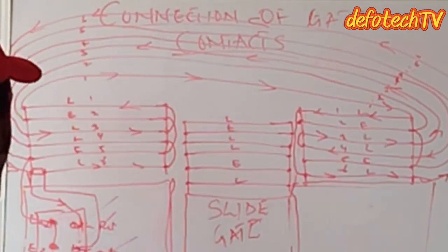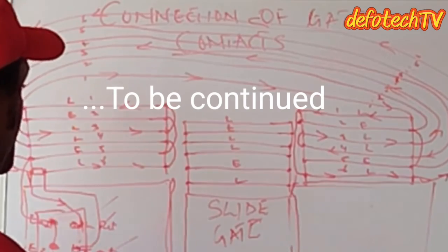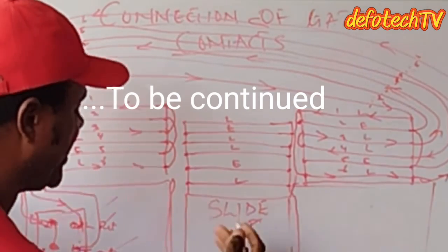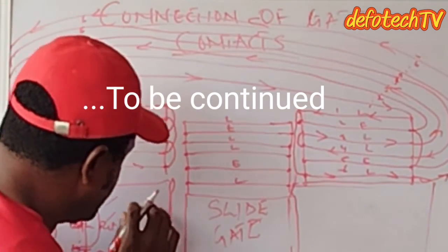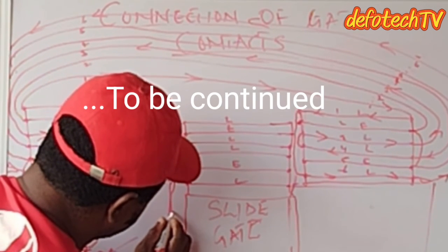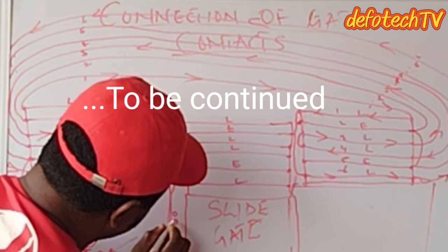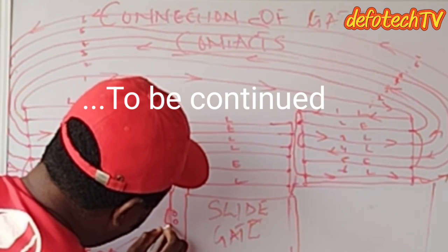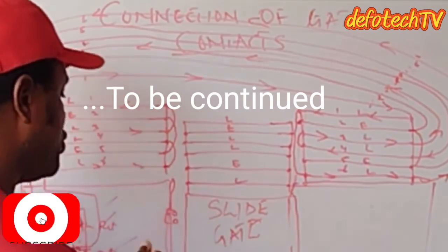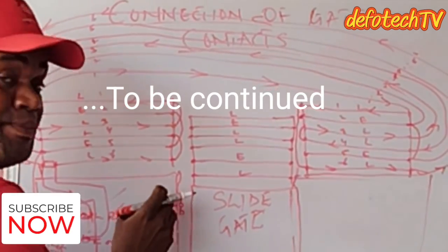Like we explained in the first diagram, we talked about where our gate contact should be. They should be on the same level. So if I come to this pillar, this area here, I need to mount my gate contact here. Now I'll put the female gate contact here. I'll mount it. I need to screw that gate contact to this place, either the fence or the pillar.